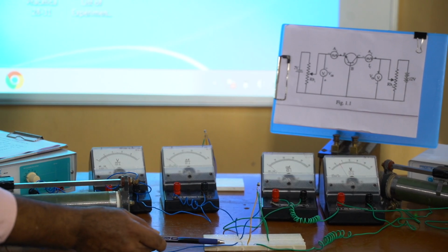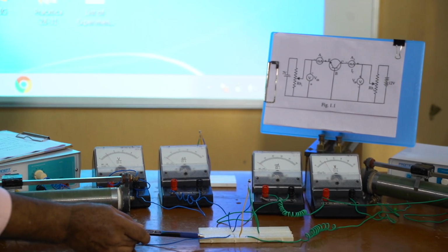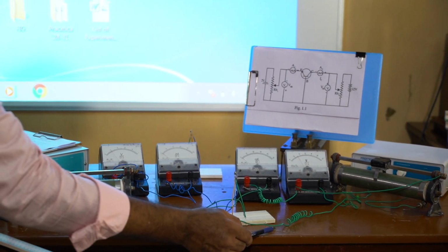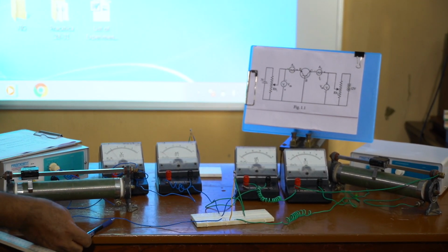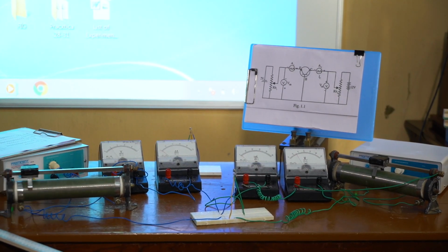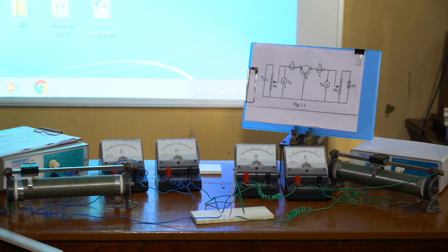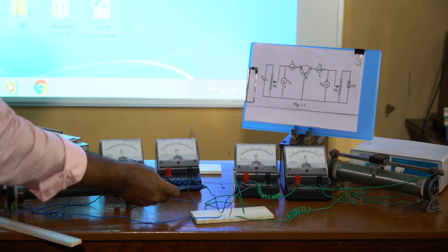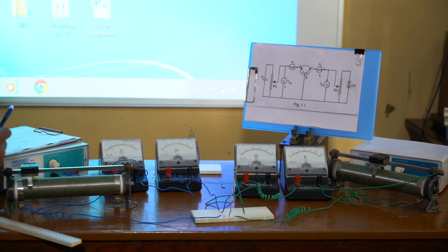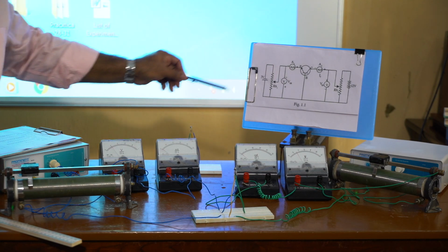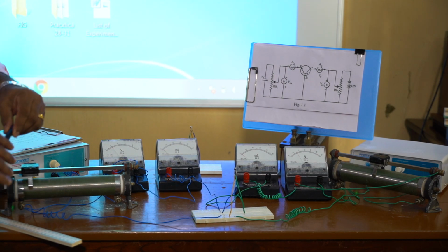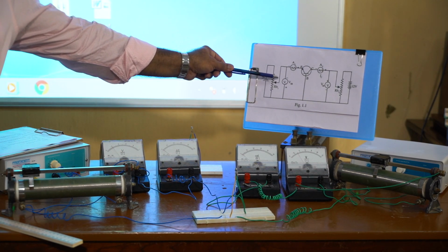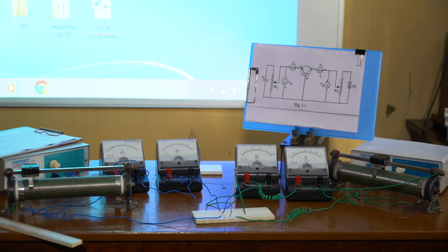Now we are taking a common terminal here on the breadboard or connection board. So that is grounded, and from that to the output side, this is the wire for the ground, and here this is the blue wire that is for the ground. For both the two sides it is grounded. Then the emitter is connected to the positive of a milliammeter. From the negative of the milliammeter, it is connected to the negative of the voltmeter, that is V1.